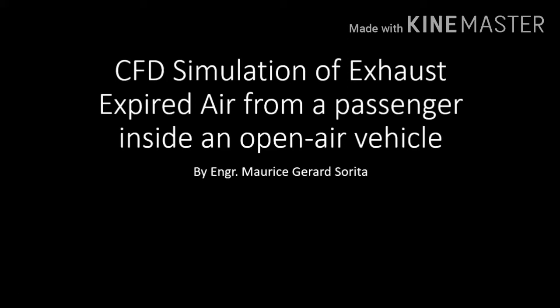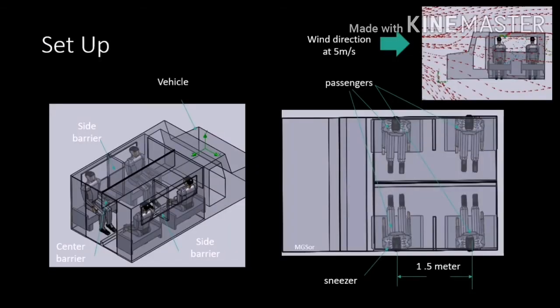So for this topic, I will be discussing CFD simulation of exhaust expired air from a passenger inside an open-air vehicle. I will be discussing the current problem that the Philippines is having right now on using a jeepney and reducing the social distancing from 1.5 meters to 0.75 meters or even further to 0.3 meters. So I have set up a CFD simulation to see what will be the flow velocity and the mass concentration of expired air inside the vehicle.